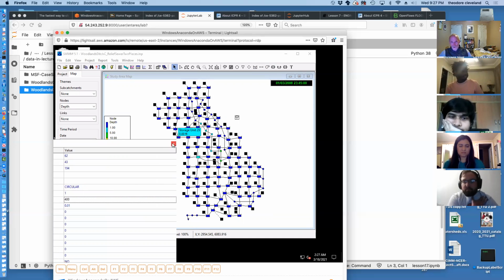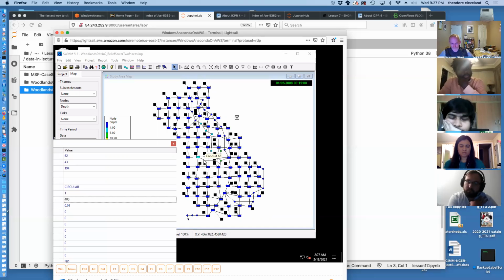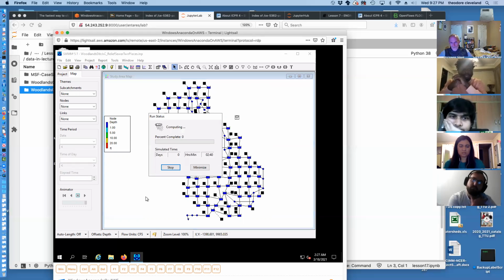Let's make it, yeah, we'll leave it at 1 foot, and that's like 280. Another 200 is 560. I'll make it a 600-foot long sewer. It's pretty long for a 1 foot diameter sewer, but we'll go with that. Rerun my simulation, and we should be able to keep that cell. It may not stay below the 1 foot level, but we'll be able to dry it out after our storm has passed through. And that's how you use these two-dimensional ICPR concept models.